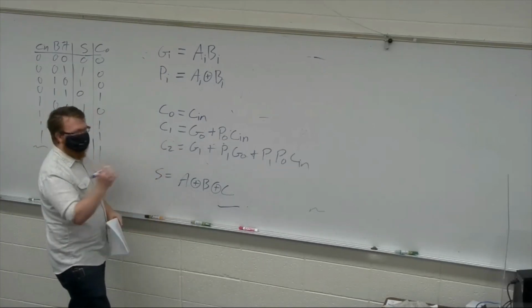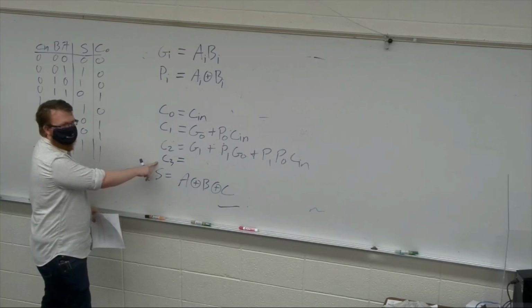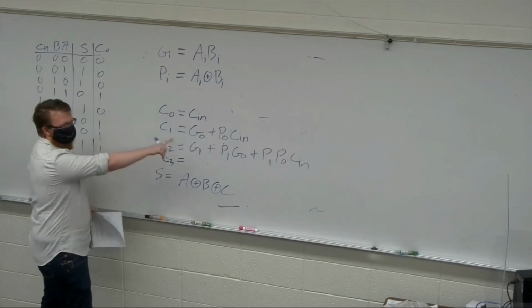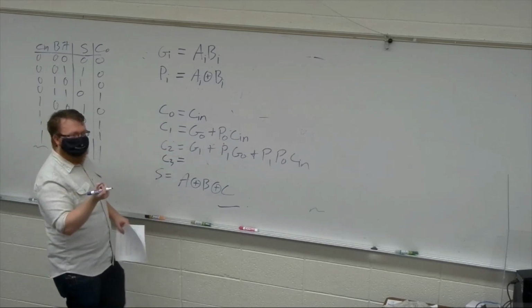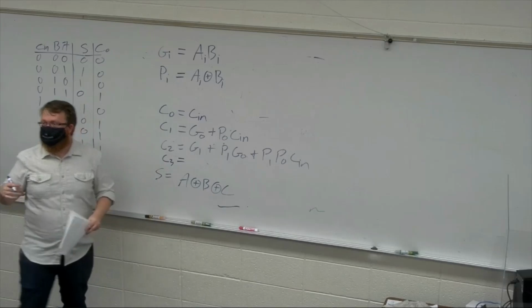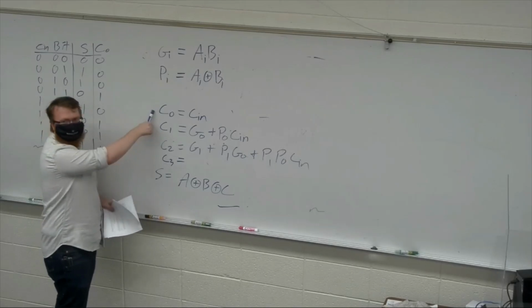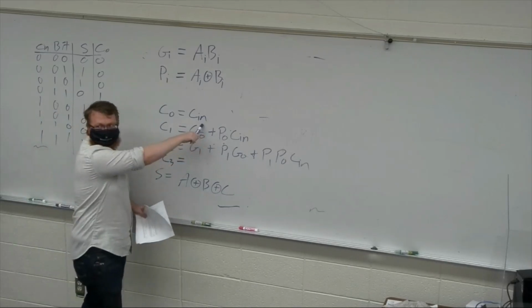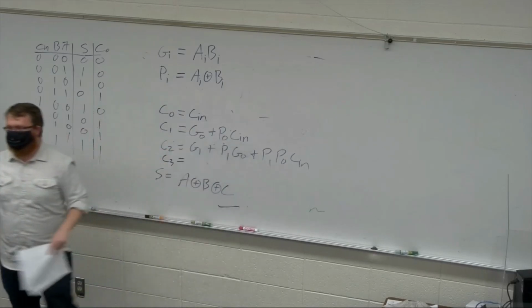So in order to do a 4-bit adder, I would normally need to see 3 of these equations. All I need for the carry out is a 4th one of basically that. And now I have a carry in and a carry out, and I can just start sticking them together with only a little bit of extra overhead for the carry out, as opposed to just building it all in one chunk. So why is there a delay in there, if each one depends on the previous? Because this one doesn't depend on C0, it only depends on the carry in, which is available from the get-go.